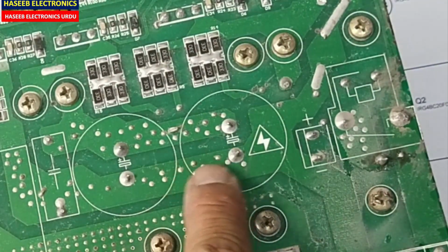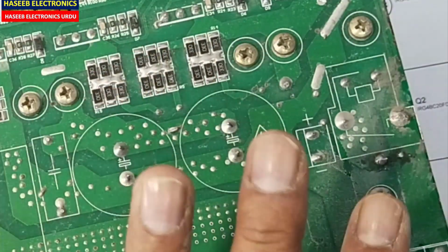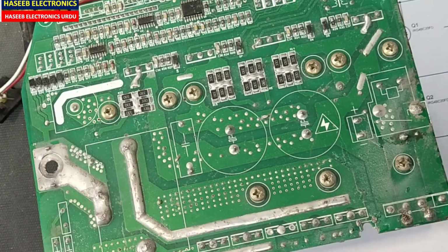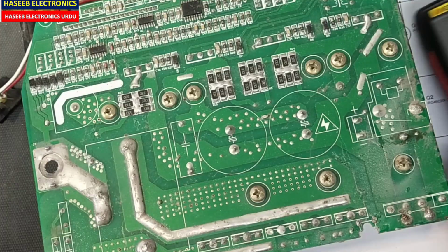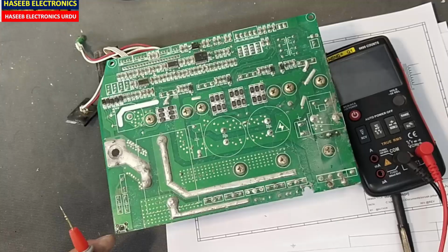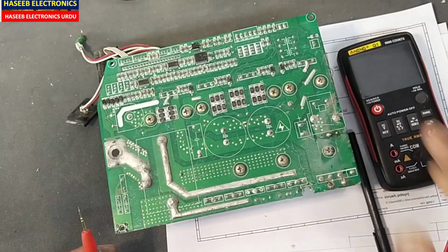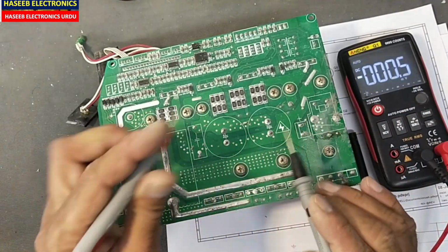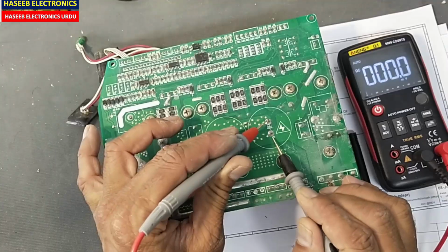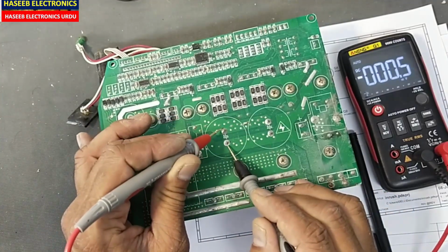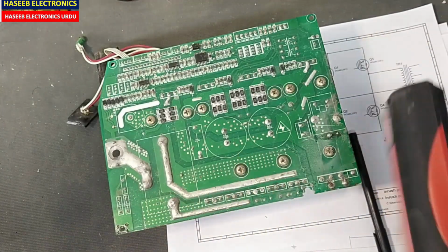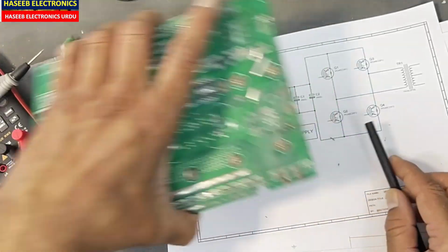These capacitors are here. Never touch any capacitor until you are confident that it is discharged. If you don't have good practical experience in power electronics, never try to repair it, never try to touch it. First of all, before touching this circuit, because it has a very huge bulk capacitor, it must be verified that it is 0 volt before touching it. Okay, let's move to the circuit.